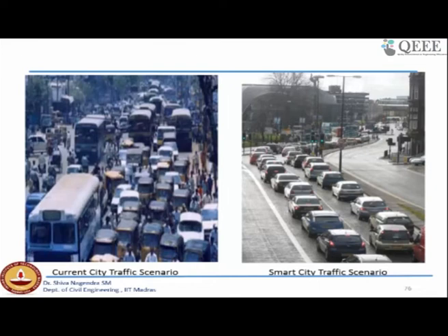Whereas in the short term, for example, you have old vehicles of more than 10 years of age, and you would still like to reduce the emissions contributed by these 10-year-old vehicles. Then you should look for some kind of arrangement to control the emissions at the tailpipe itself. For example, fitting a catalytic converter or a filter, so that can also reduce the emissions